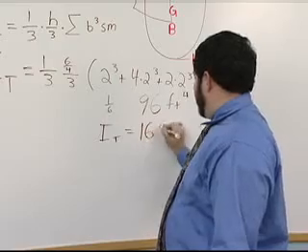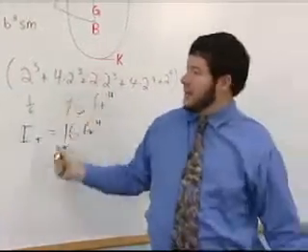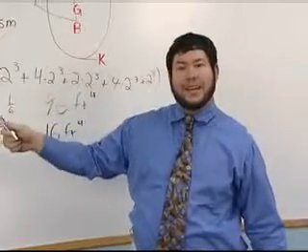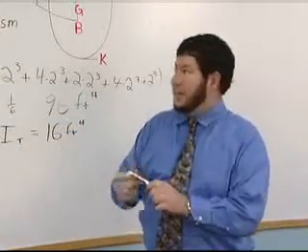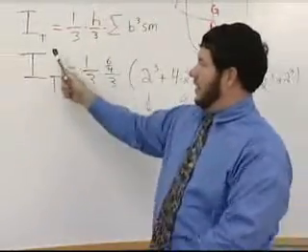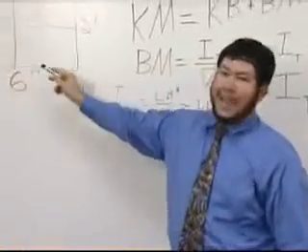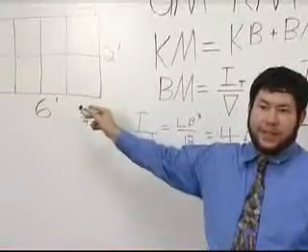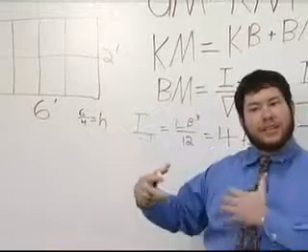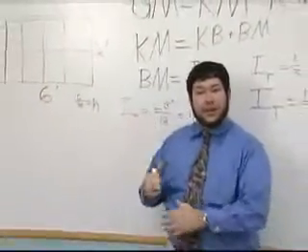You'll notice that this 16 does not agree with the 4 that we calculated before. And that's because, as I said before, this formulation calculates the transverse moment of inertia about the one edge of the shape rather than about the center of the shape. But we need the center of the shape for our equation.